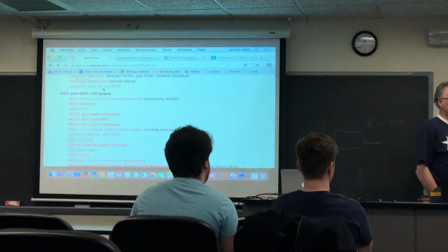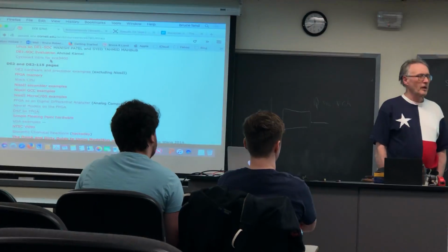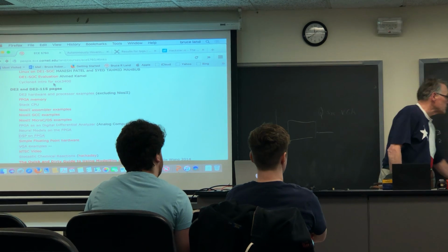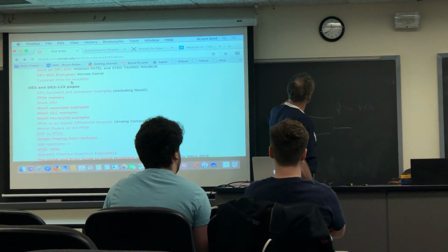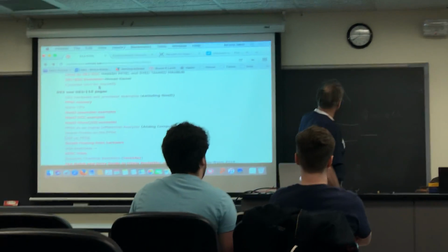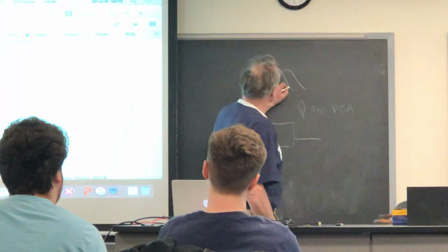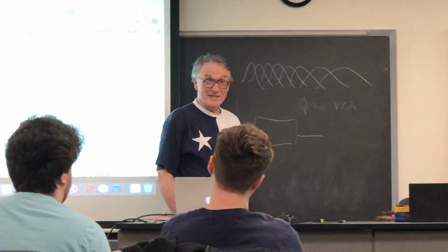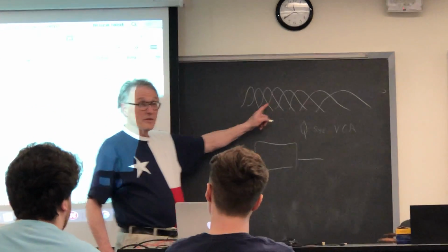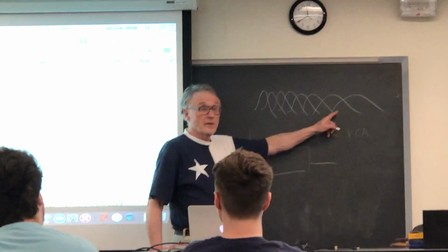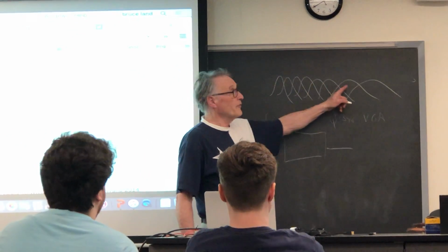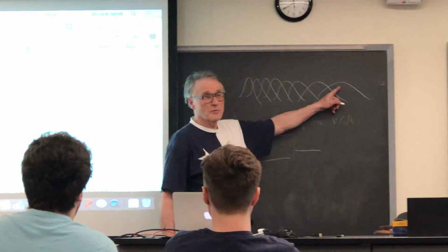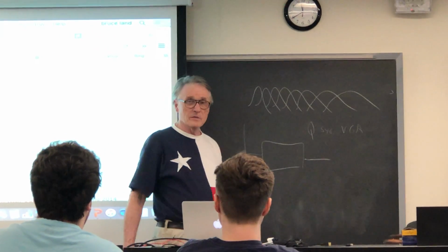Well, if you can build a bunch of fast filters, why bother to do an FFT? Why not just build a bunch of narrow filters? And the advantage here is that you get to change the bandwidth of each filter so that, on a log F scale, the bandwidth is a constant fraction of the frequency as opposed to a constant bandwidth like it is with an FFT.